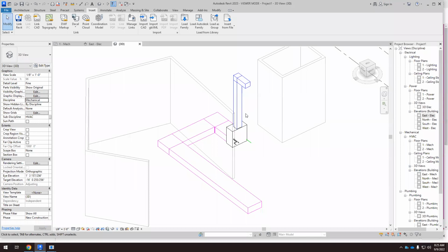If you have any idea of systems, if you have any idea about the thickness of this duct, you can foresee how much space you need from here until the structural element. I need 3 feet. Okay, so I design 3 feet. It's not just, okay, I have all this, and you get the file back from the other company. No, you need 3 feet.